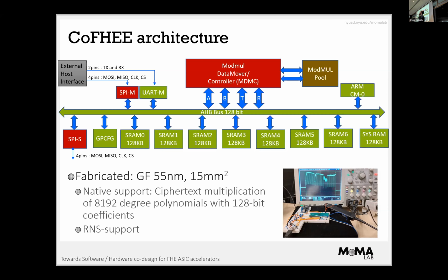Why not RISC-V? Well, I'm not sure how big RISC-V is. This is extremely small. I don't know about RISC-V. That's what ARM gave us, as a macro. If it's a macro, it already works, so you have guarantees about its users. If you want to do your RISC-V backend from the beginning, then I'm not sure how successful it would have been. But again, it's a very tiny macro. We added it, and it's also easy for us to program in ARM assembly. But you're right, it could be any processor, it can be RISC-V too.